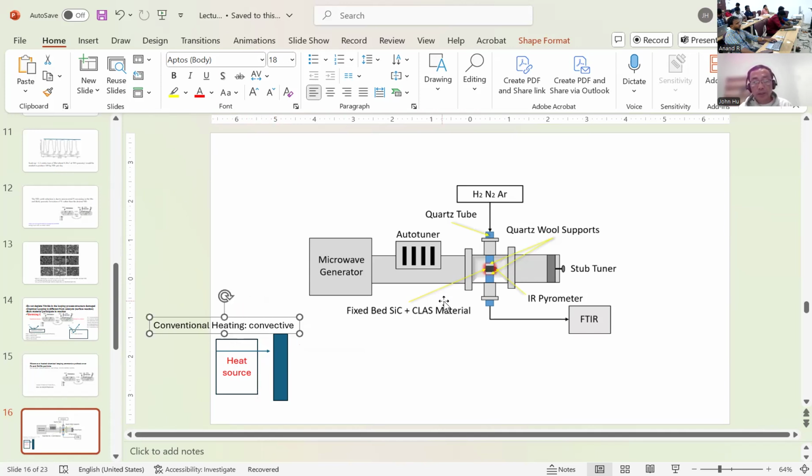Okay. With microwave heating, you have the microwave field passing through the material back and forth, and the energy is delivered as an electromagnetic field. Then it induces the heating. So it's targeted heating, selective heating. It's not really convective heating. Convective heating means you heat from the external to the internal. Microwave heating is heating from inside out, so heat transfer actually goes from inside to the outside, because it's field delivery rather than convective heating.